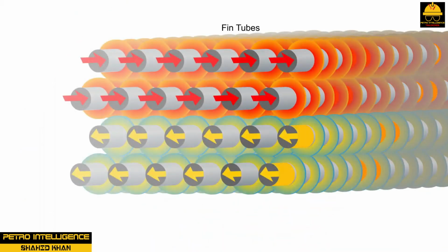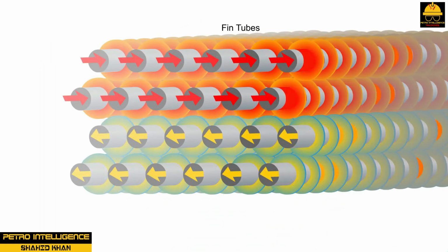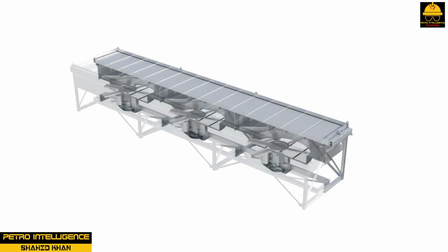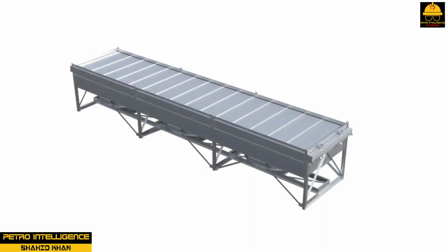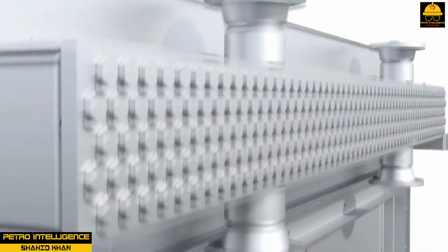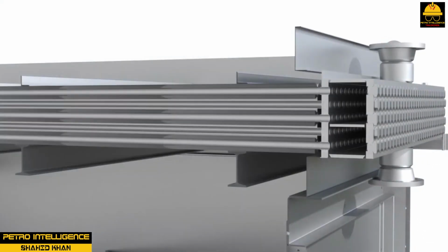Mechanical fans use a variety of drivers. Common drivers found in service with air-cooled heat exchangers include electric motor and reduction gears, steam turbine or gas engine, belt drives, and hydraulic motors. The fan blades are composed of aluminum or plastic.